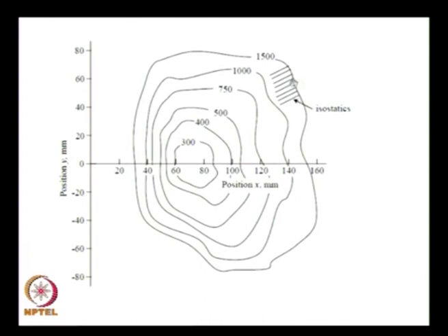So, the idea is definitely at the end of these cracks you will have the failure strain of the coating is reached at that point in the specimen, but this is obtained for a load of 1500 newtons and this contour is obtained at for 300 newtons and so on.